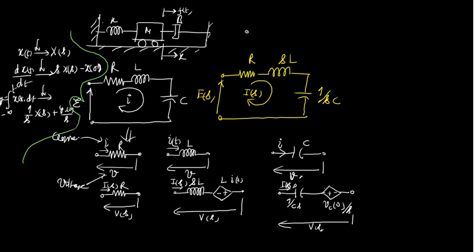Like in some cases when you ask about the transfer function, you can write down the KVL again. It is a rising potential, we are moving in the direction of current, so it is minus Is R, then minus Is SL, and then minus 1 by SC Is, equal to 0.